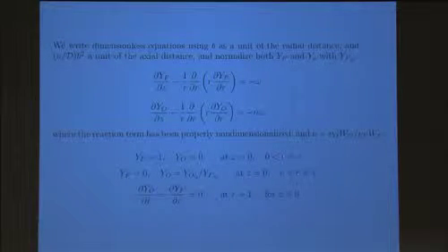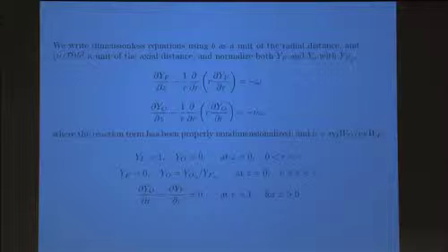So the radius goes from 0 to 1, and C is the ratio of the inner to the outer cylinder radius, okay? So C is where the inner cylinder ends and the outer cylinder starts. And then YF and YO were normalized with respect to the fuel mass fraction. So the fuel mass fraction is 1 in the fuel region, and the oxidizer mass fraction is just the ratio of oxidizer to fuel. Okay, so this is just a simple normalization.